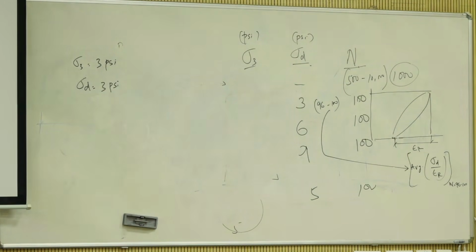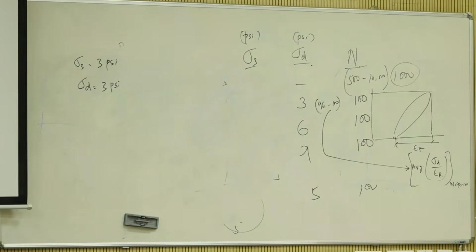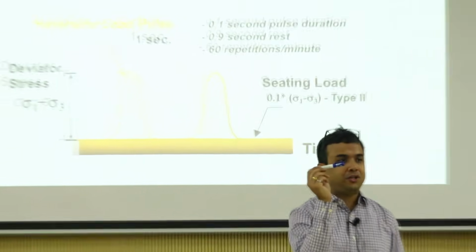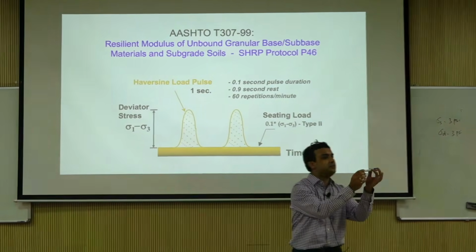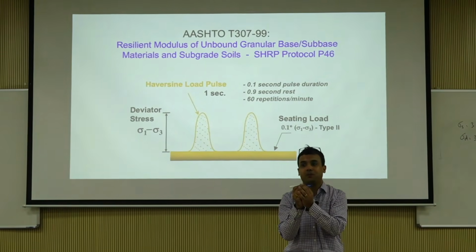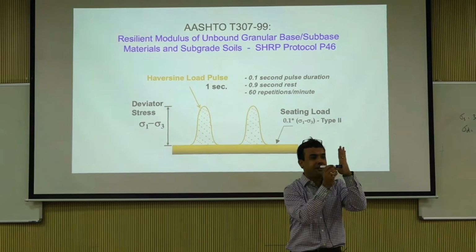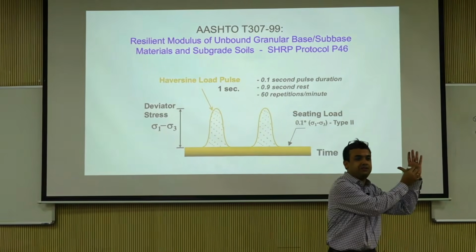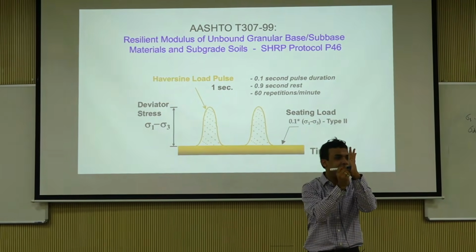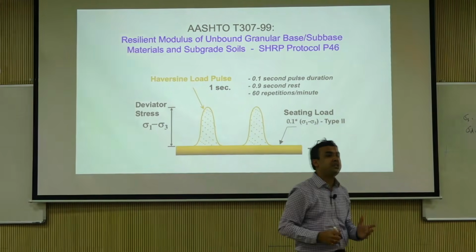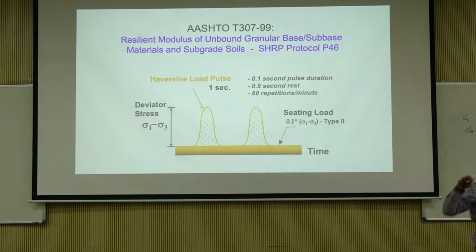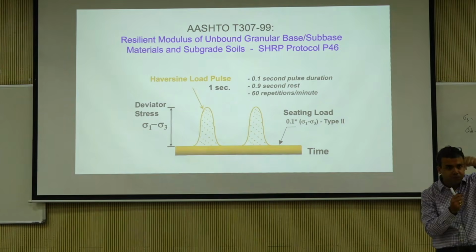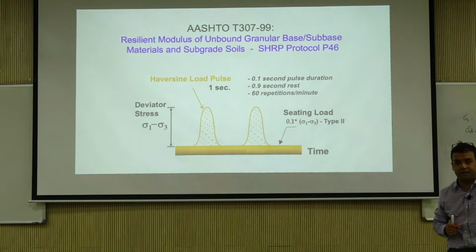Now my question is, yesterday if you paid attention, I alluded to this. I said a device only knows how much to move because displacement is an absolute measurement. This is 0, this is 1, this is 2. It's very easy. Force is not an absolute measurement. Force is dependent on my material. If I'm trying to push and my hand is moving, force is 0, whereas if this is constant, it's very big, right? So the question is, even if it is a stress controlled test, in the background the machine is actually going by movement. There is a problem with that.